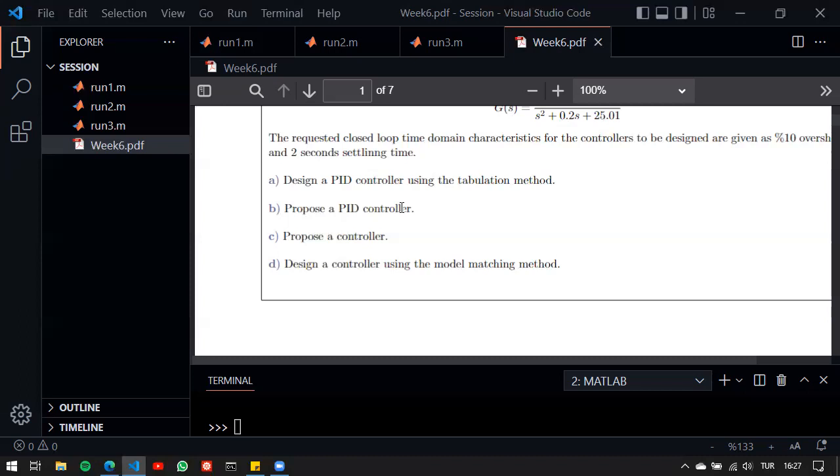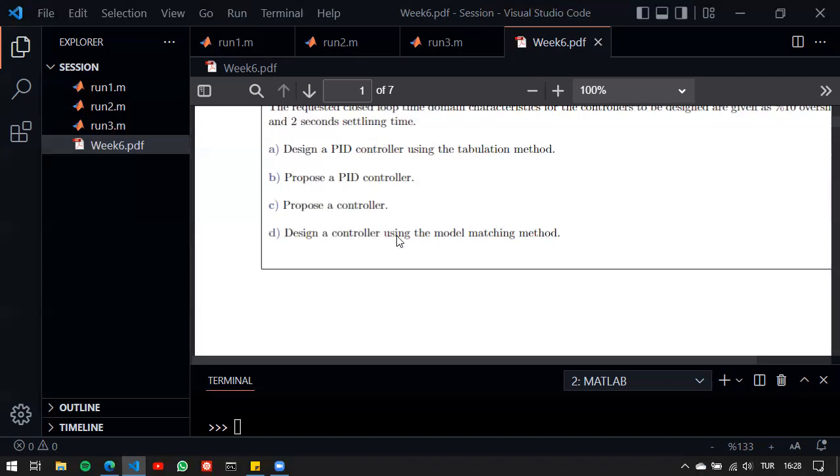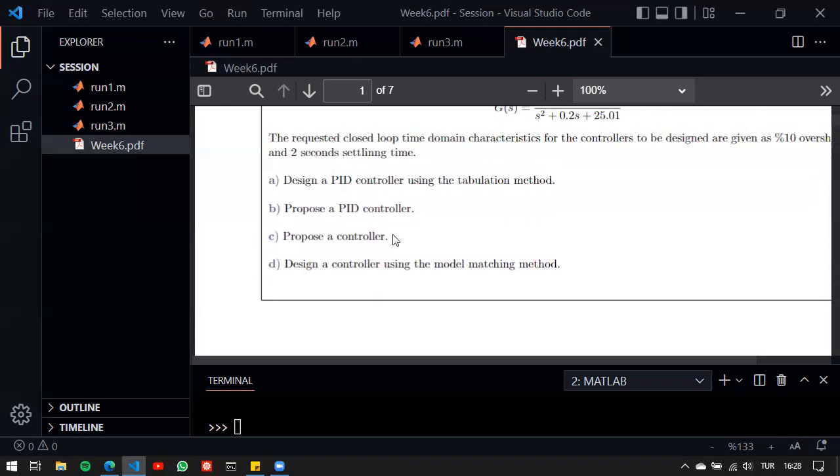So for most systems, it seems like overshoot is not really something that is desired, but for example, for some sensors, you might have already 10% variation in your parameters, so you might tolerate that. In cases where settling time is important and overshoot is allowable, then there is a design that might give you some overshoot. There might also be cases where overshoot is really relevant, but I cannot think of one at the moment. So what about the model matching controller?